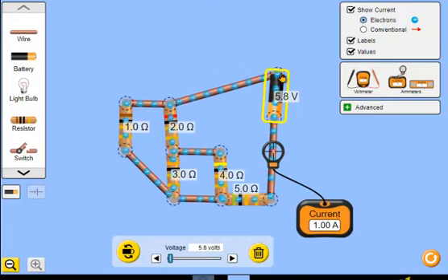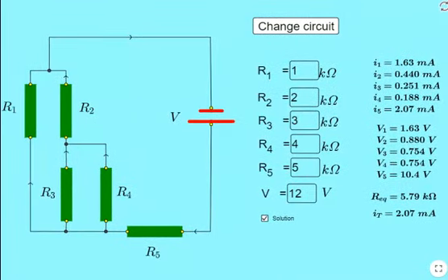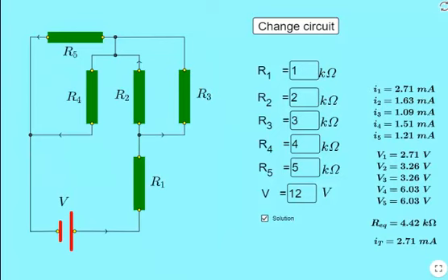All right, I continue on here. Going to push this one in here, go to the next circuit that he has, so change to the circuit here. Looks a little bit more complicated, but I think we can see that R1 is in series with all the rest here. And then we see how we analyze that. And there's a junction. This is actually one and the same junction, so in between 4 and 5 and 2 and 3 over here. And if you look carefully, then you see that 4 and 5 are in parallel with each other. 2 and 3 are in parallel with each other. And then all of the stuff here, these 2 over here, these 2 over here, and the 1 here are in series with each other.